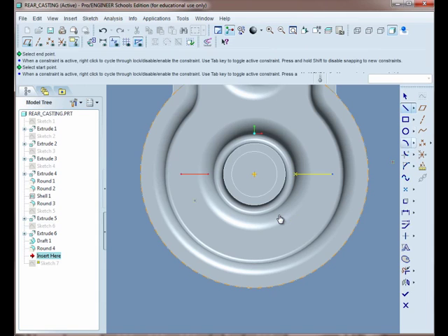So what we can use instead, if we hit the little arrow to the right of line, find center line, or geometry center line, and then click on that center point and drag it straight up to make a center line. Now you could go back to the ordinary line tool here, and right about there click and drag out a little horizontal line, a little vertical line. Middle click a couple times and some dimensions will appear. If you want, you could adjust them, but they're already locked in to vertical and horizontal relationships to the center of the circle. So we could just hit Done.